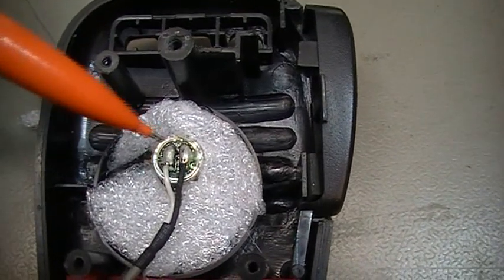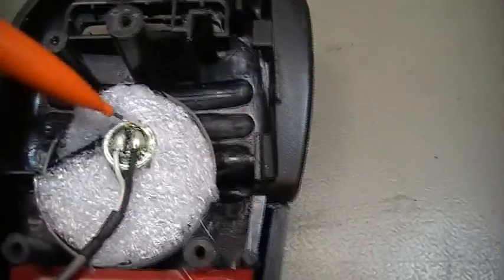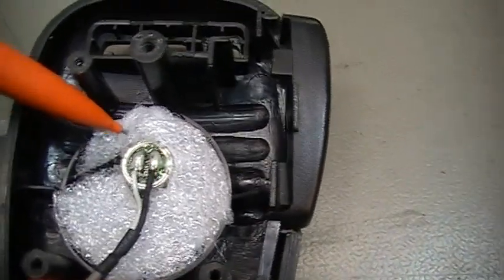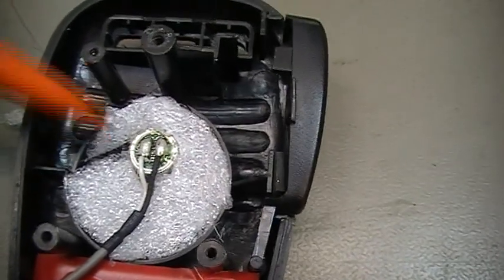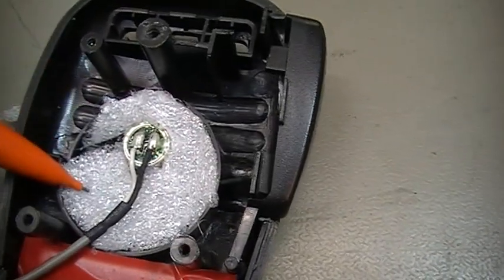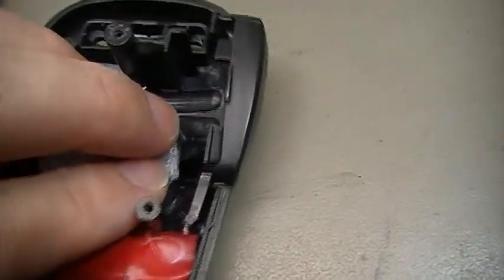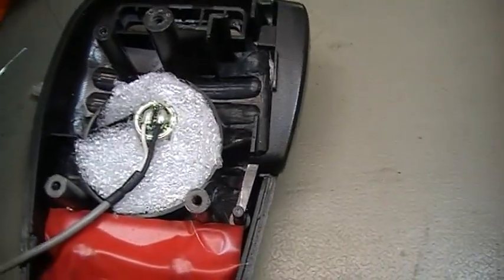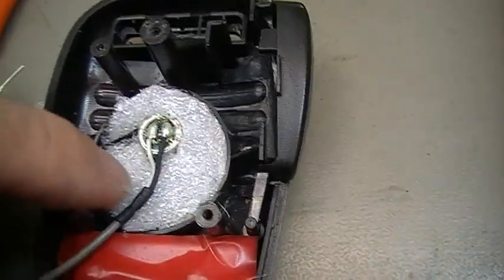The new capsule is in, glued with hot glue, and I have already put some foam around it, which is essential so that the capsule will have a good sound. Now I will cover it with some additional foam so that it is closed all around, and then we hope that we will have a nice and clear modulation.